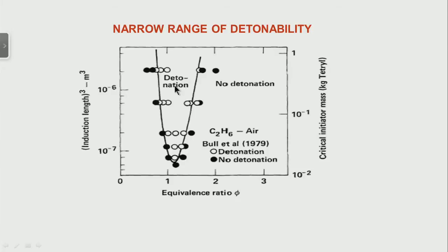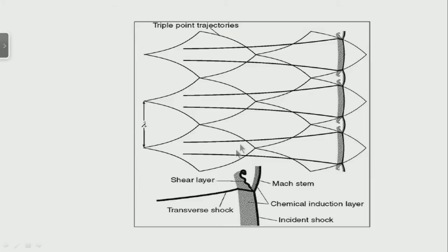What causes these detonability limits? I think we have to take another look at it, and therefore, in the next slide I again go back and show you the 3-dimensional structure of a detonation. You have transverse waves over here. Supposing within a particular pipe or region I have just 1 or 2 of these cells, that means the cells are very large, and I have no way in which these transverse waves, when they come over here, can hit each other and create another cell of a detonation.